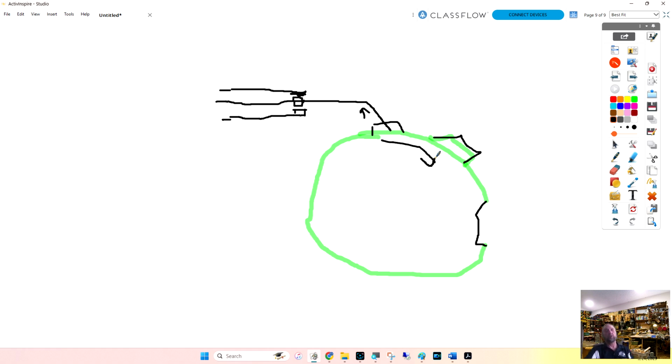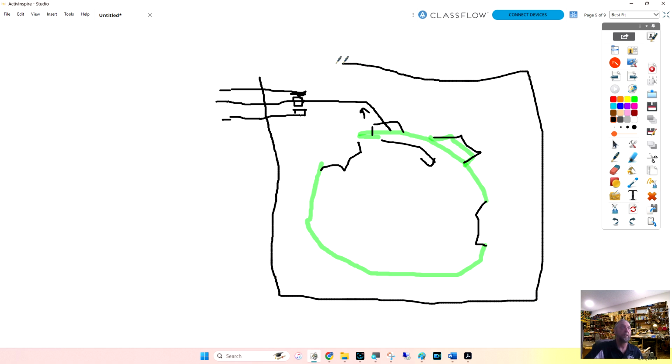So as the timer's rotating, pieces would raise this up, or we'd get into a piece that was cut out here. And then what would happen? It would drop down and make connection to the bottom. So we'd have wires. Well, let's just do this. This would be our timer. Our timer motor would be here, and there'd be gears that would rotate this. And then our wires would be connected here.